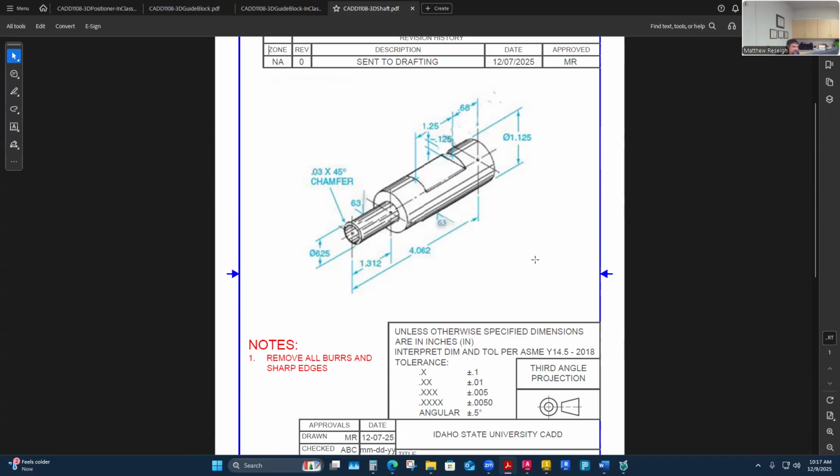But really, it's only going to take two views of this. It's going to take a front view to show kind of the diameters, at least as a view. I might not call out the diameters in the front view because I'm also going to have a right side view where those diameters are going to appear rectangular, and I'm going to probably call out their diameters in the rectangular view in the right side view. But what I'm going to do is just pre-plan ahead that front view is going to be looking dead on the shaft as just circles, and my right side view is going to be the linear, kind of the depth of the part, essentially.